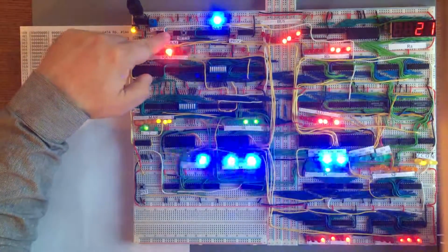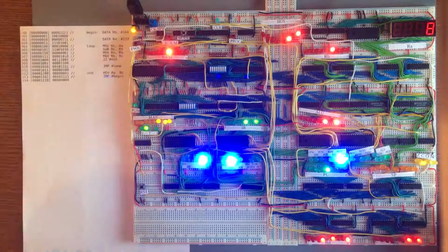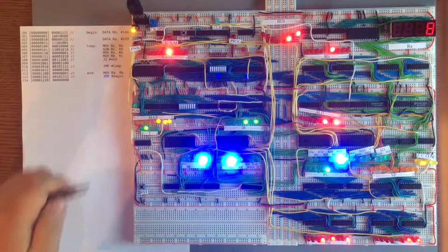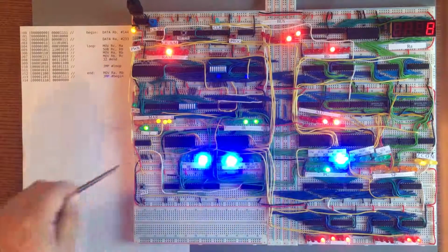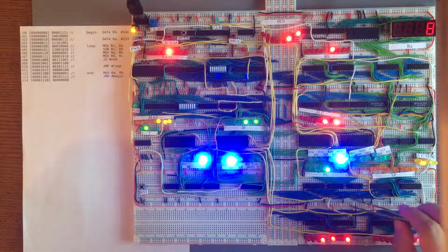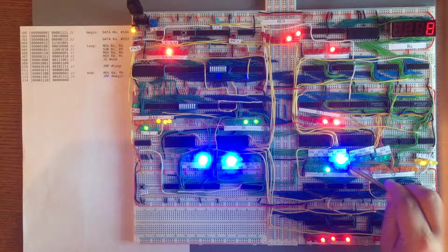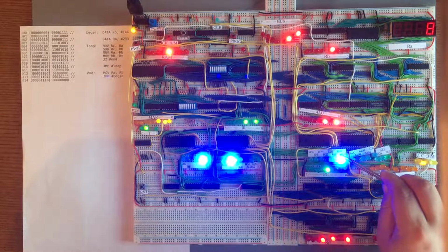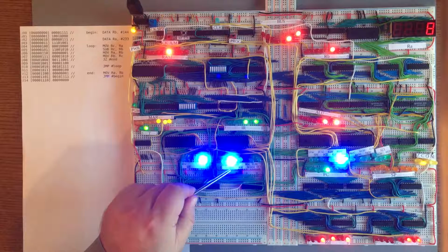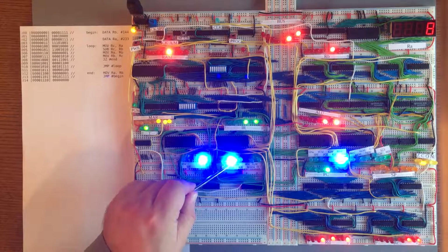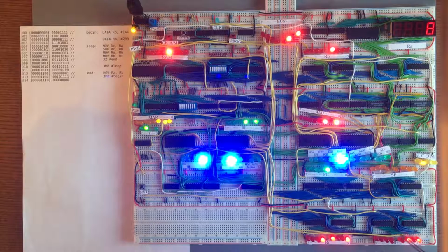So if I just turn the clock to manual mode just for a moment. At this moment we're going to get to the control logic, which is all of this area down here. But two things I want to point out is that at the moment there are two signals which are on, and that's this signal here, which is register B write, RBW, so that's this LED. And another signal that's on right now is register C enable. That's this signal. And so what that means is that this is the C register over here. And so at the moment that contains a binary value of 5.